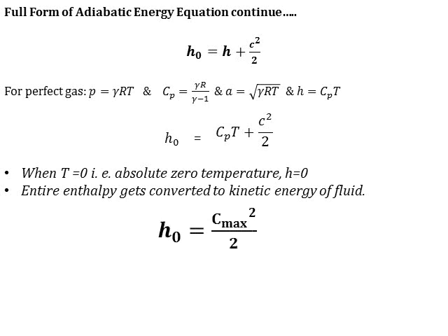That means now the kinetic energy of the fluid is maximum because it is equal to the total energy, or the maximum energy possessed by the fluid. And the velocity corresponding to the maximum kinetic energy will also be the maximum possible fluid velocity and is also referred to as the isentropic velocity of fluid.